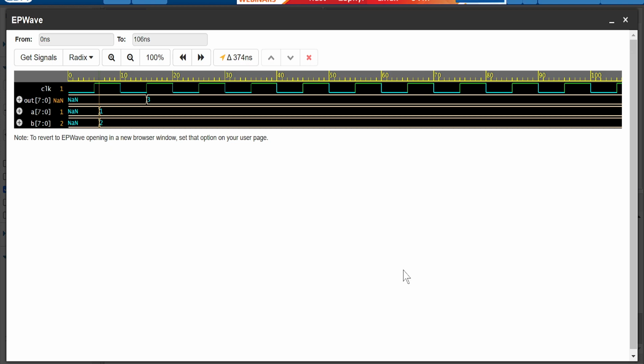You see this thing, it is very clearly visible that I have missed this time frame of 5. So I have put my input signal at the 6 nanosecond. The output is getting updated at the next positive edge of the cycle, right? So this is the next positive cycle which I'm showing over here. You can see the results are coming at 5, 10 and 15 nanosecond. Although I'm giving my input at 6 nanosecond, my output is coming at 15 nanosecond. So this is a sequential circuit.